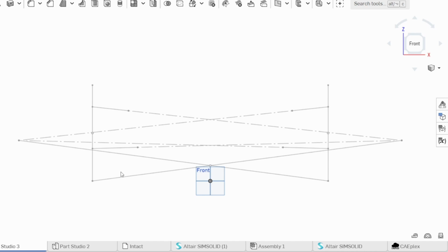And this is important if you have aerodynamics, front and rear wings, spoiler, under tray, whatever you may have. They're all going to change the coefficient of drag and coefficient of downforce depending on the ride height. So if you have an aeromap that maps out front and rear ride height versus drag and downforce, then jacking force is definitely needed, so you can use that aeromap in your simulations.